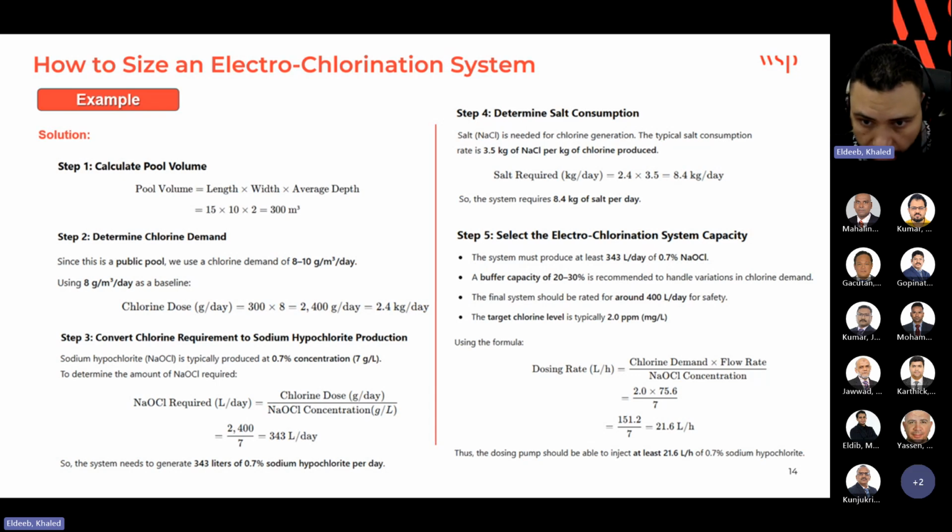Regarding the head of the pump, it depends on the system back pressure, which needs to be slightly higher to dose the flow. So let's say if you have 2 or 3 bar system pressure, you can make it slightly higher, around 0.7 bar or maybe 1 bar, because you need to overcome this back pressure coming from the system. So you have the flow and the pressure. Now the dosing pump is calculated.